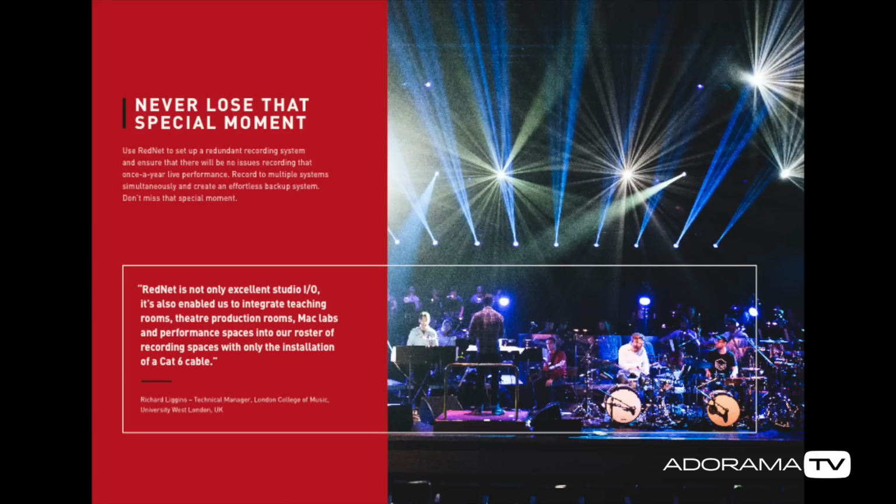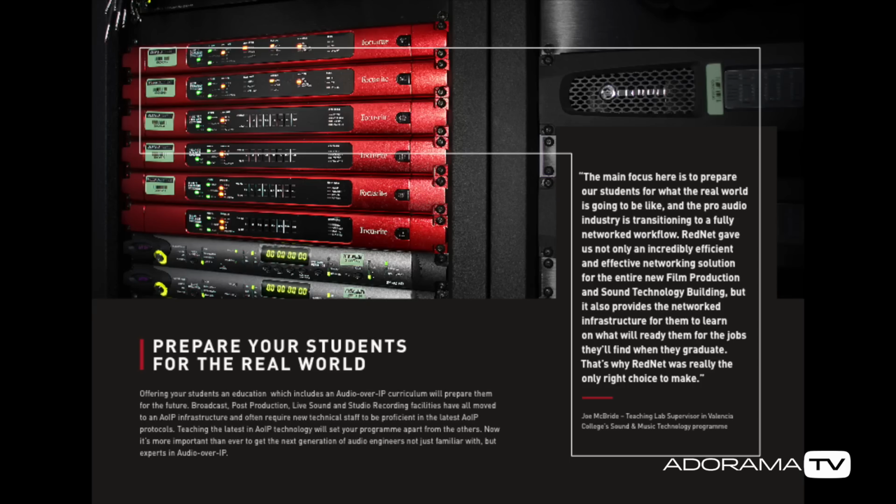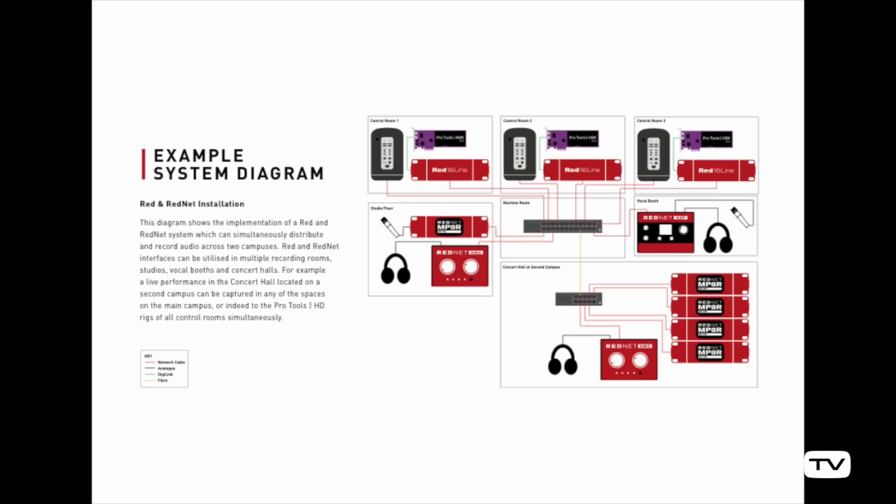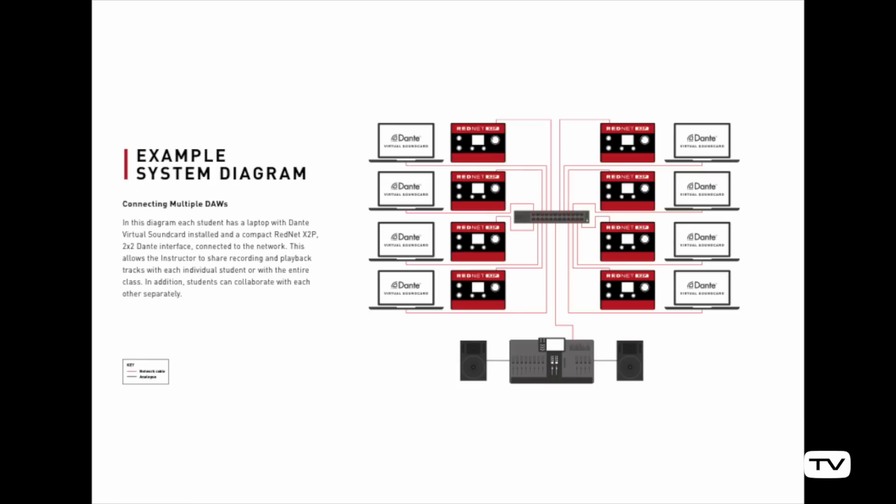Amazing. So audio over IP is the big thing here this year. In the very simplest terms, could you give an explanation to our audience? Absolutely. So essentially, audio over IP allows us to take a standard network, like we use with our computers every day, and send audio back and forth across it in an uncompressed format from one to many devices using the same cabling that we're already familiar with.